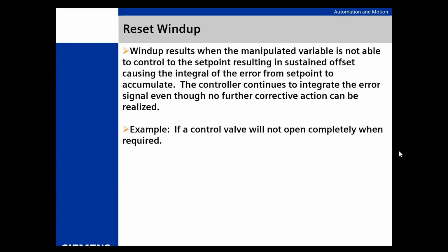The controller is going to keep trying, and keep trying. Now, if it's got the adaptive feature, it's going to wind up. What wind up means is that little bit of error gets bigger and bigger and bigger and faster. Okay? And now people will tell you, well, we have this anti-wind up stuff in our algorithm. Well, good, but it's not guaranteed.